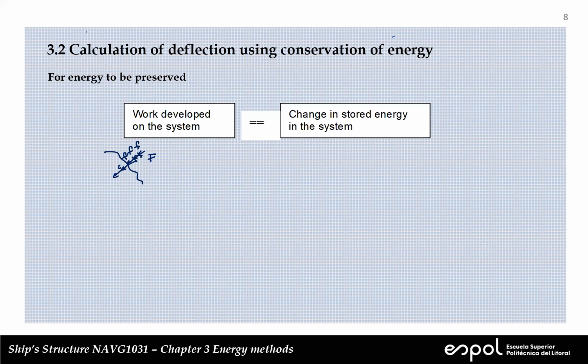Okay, so when you have two F, you displace one F, one delta only. That's the way it was explained in the video. So at the end, the work is going to be equal to 1/2 F times delta. Why? Because the application of the force is not all at once, but slowly increasing, to avoid any dynamic effect. So we spent the previous subchapter talking about U.